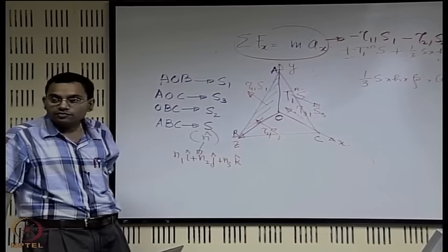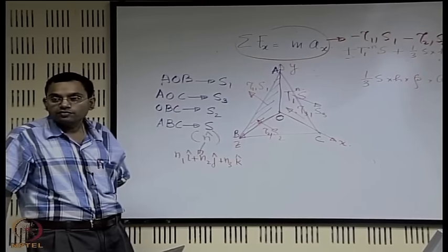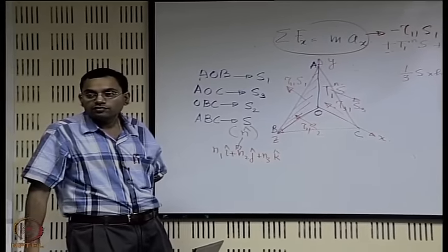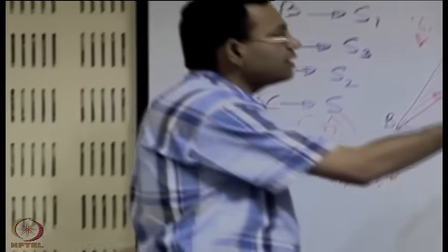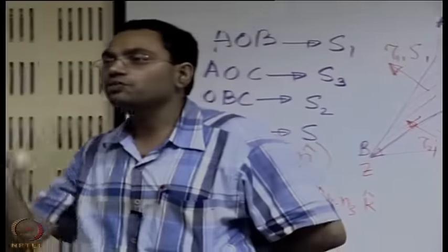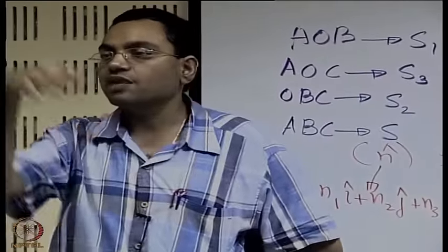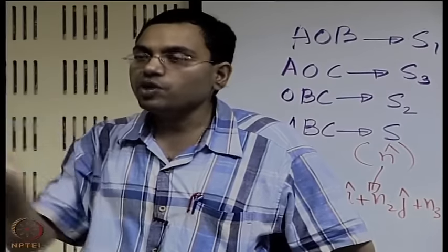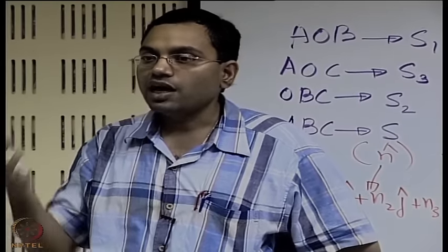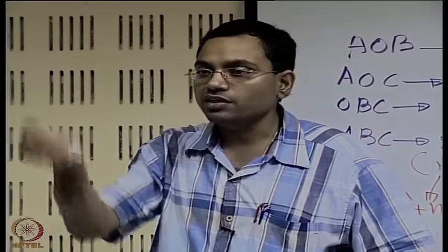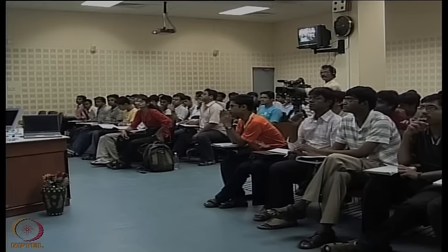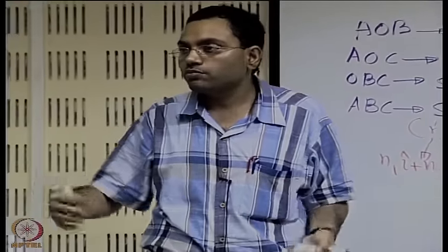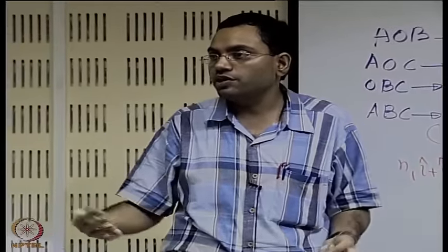Can you interpret physically what is surface force and body force? The physical definition and the mathematical definition is identical here. Surface force is a force which is distributed over the surface, which is the envelope of the volume that is being considered, and body force is something which is acting within the volume of the body. Shear force is a surface force as an example. Also normal force, just like pressure, is a normal component, not a shear component.